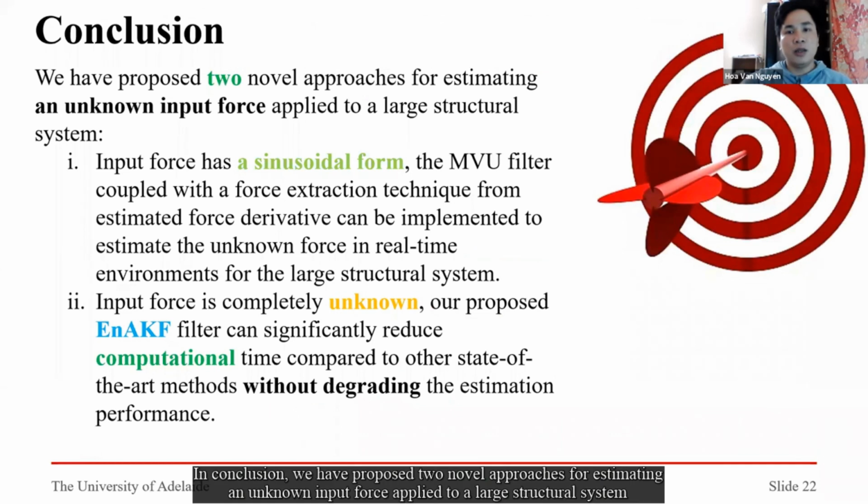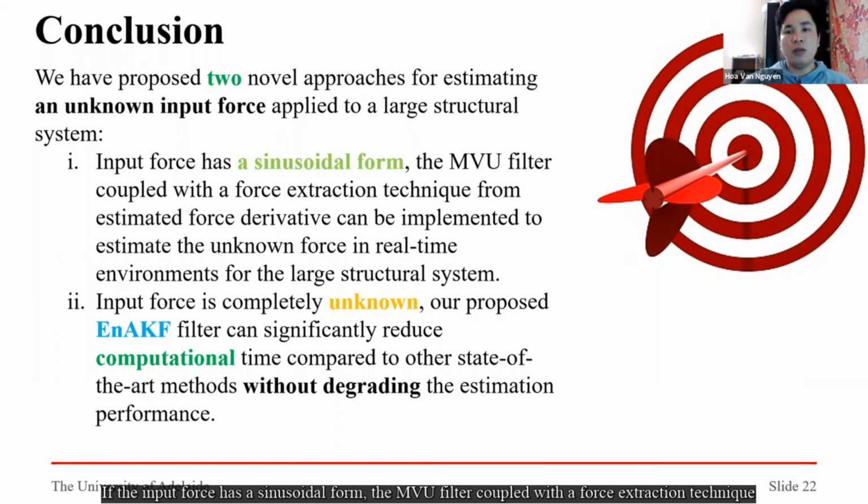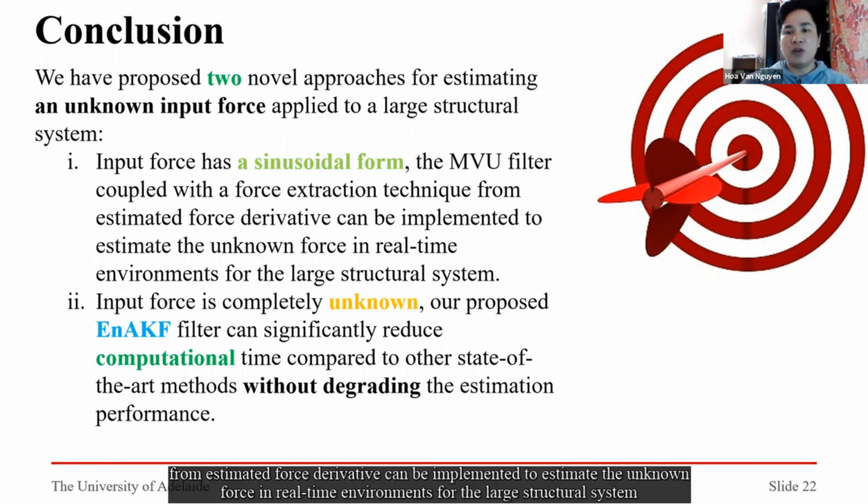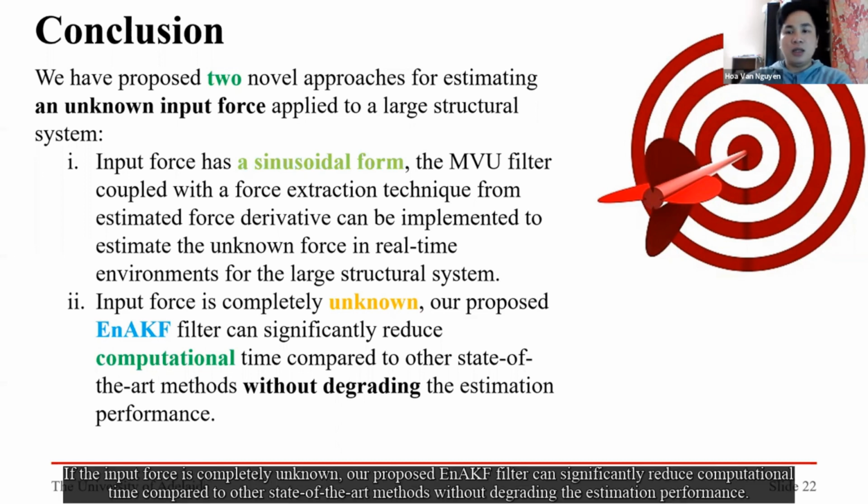In conclusion, we have proposed two novel approaches for estimating an unknown input force applied to a large structural system. If the input force has a sinusoidal form, the MVU filter coupled with a force extraction technique can be implemented to estimate the unknown force in real-time environments for the large structural system. If the input force is completely unknown, our proposed ENAKF filter can significantly reduce computational time compared to other state-of-the-art methods without degrading the estimation performance.